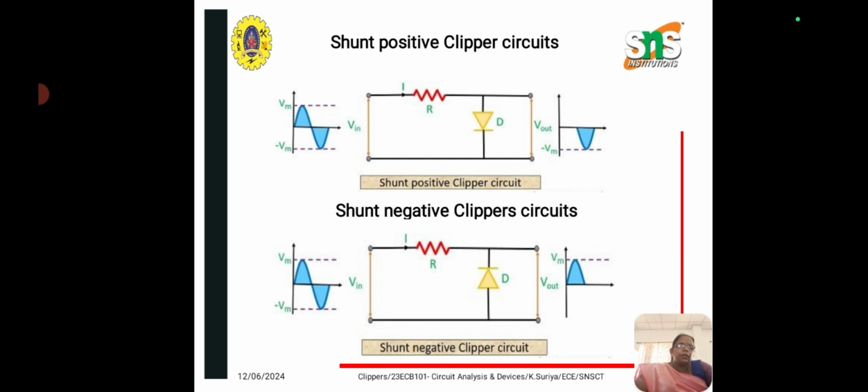During the positive cycle, the diode is forward biased, due to which the current flows through the diode. Hence, due to the parallel combination of diode and the load, no current is observed at the load. Resultantly, no output waveform for the positive half is achieved. During the negative half, the diode gets reverse biased, thus no current flows through it and the output current is observed at the load. So, for the negative half of input, the entire negative half appears at the output.